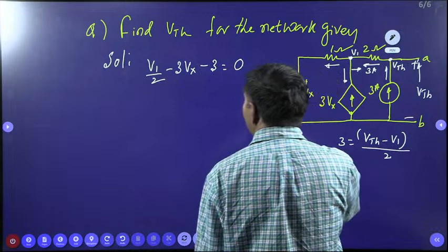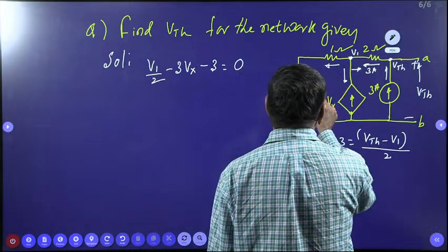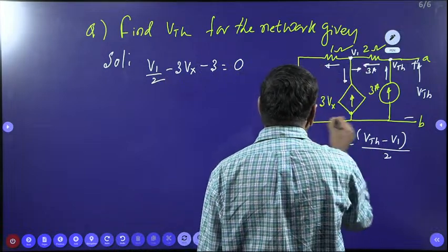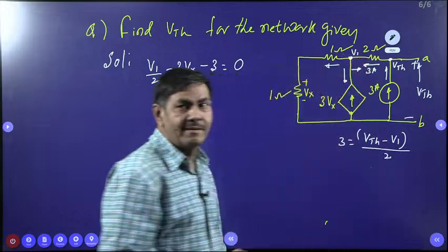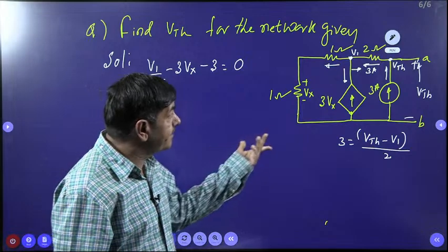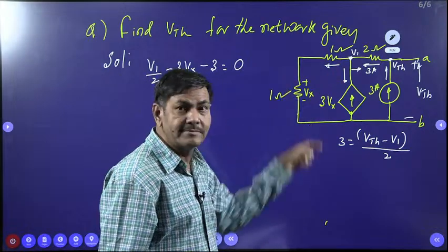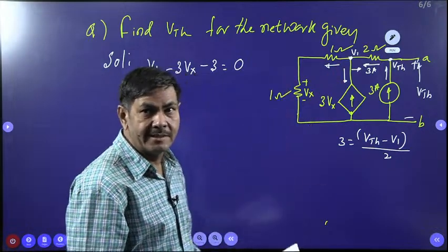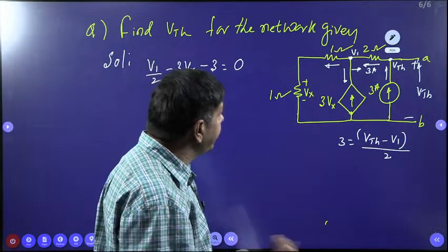Yes, here I want to get the Vx value now. Vx is nothing but here I can apply voltage divider formula. Why can I apply the voltage divider formula? The current is passing same across 2 resistors here now. It doesn't have any deviation. It doesn't divert across any other branches now.